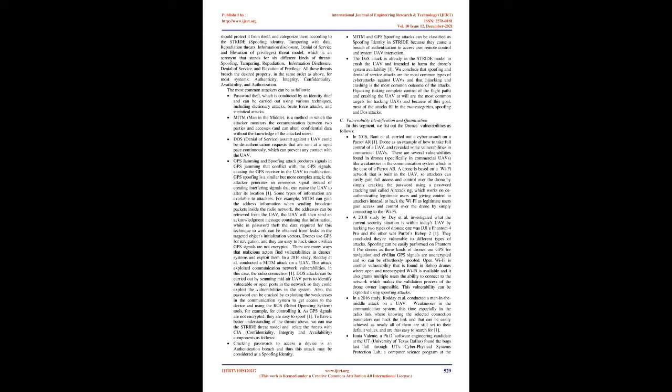Also, the password can be cracked by exploiting the weaknesses in the communication system to get access to the device and using the ROS, robot operating system, tools, for example, for controlling it. As GPS signals are not encrypted, they are easy to spoof. To have a better understanding of the threats above, we can use the STRIDE threat model and relate the threats with CIA, confidentiality, integrity, and availability, components as follows.